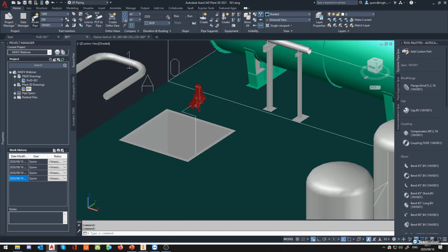Such as, when you're routing your pipes, yes, you do have these little numbers. Now, just a little tip here, you can actually use these numbers, and this is part of the reason why it helps to work with both P&ID and 3D: you can use this as a checklist. If you think you've routed all your pipes, and then all of a sudden you look in your line list over here and say, hey, wait a second, I've still got pipes remaining, it's a good indication that you need to go back and take a look at what's happening.